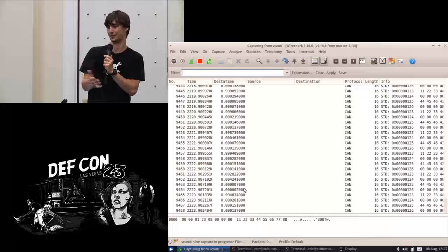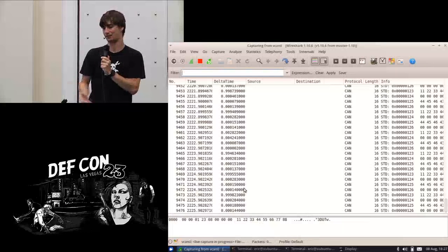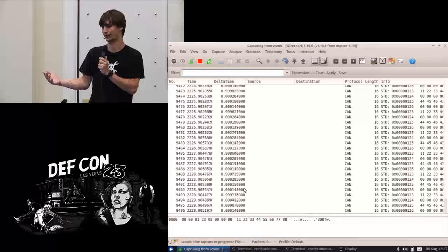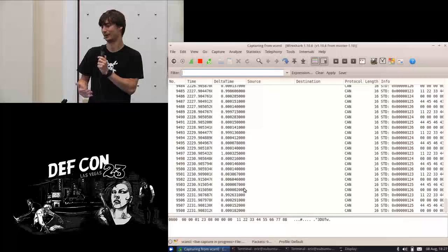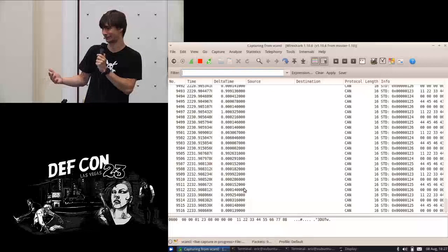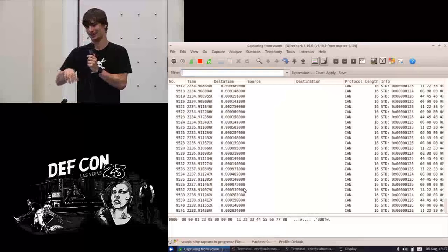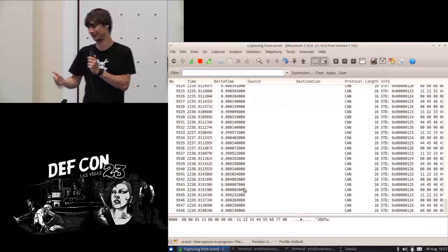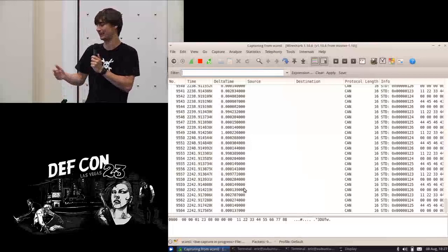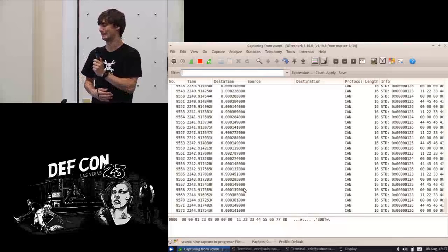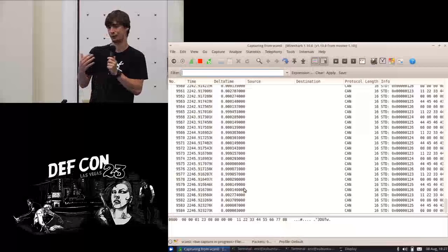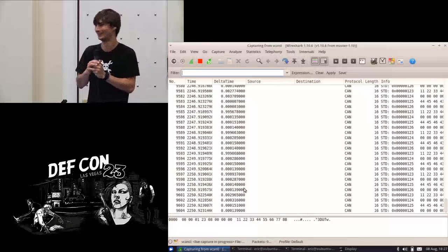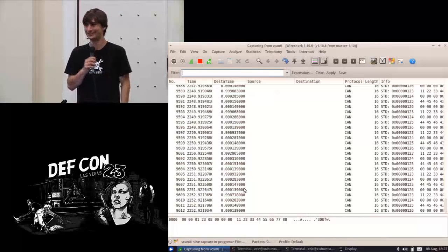So what often happens is you buy something from an OEM, it only supports CAN ID 100 and 101, and they want to charge you like 10 grand to change it to 102 and 104 or whatever. So you put a device in the middle and you make it do that translation for you because it's cheaper. For stuff like that, VCAN can be pretty useful. But in terms of actually knowing who's talking to who, unfortunately, CAN is pretty good at hiding that from you. Makes a lot of other stuff available, though.